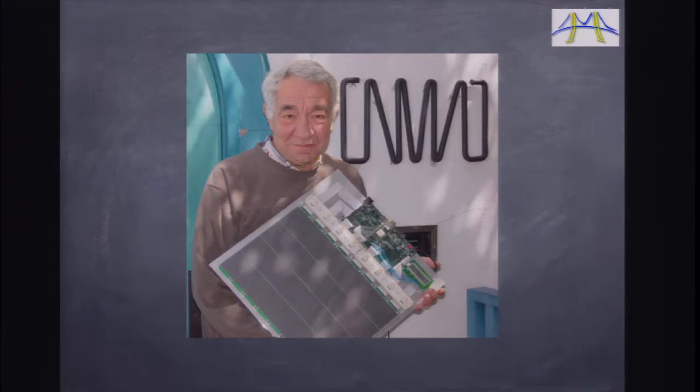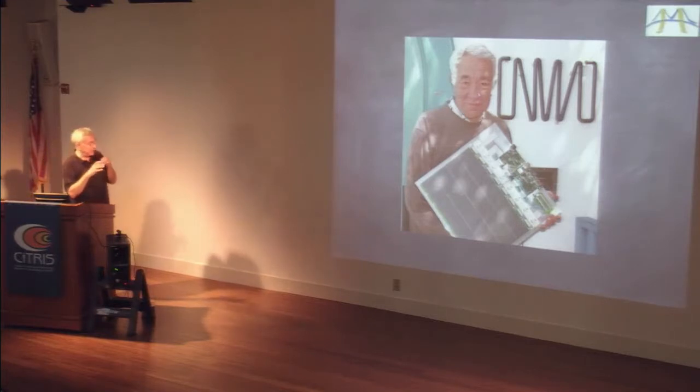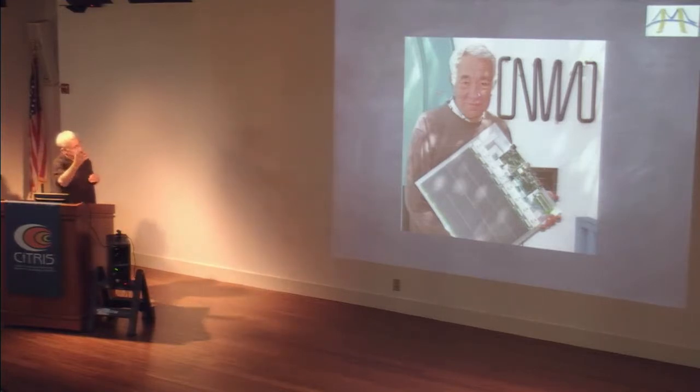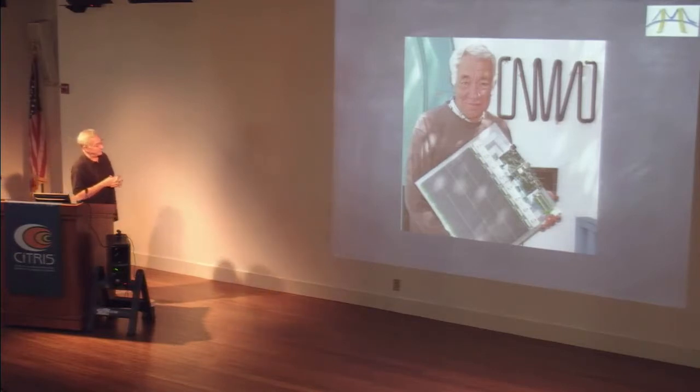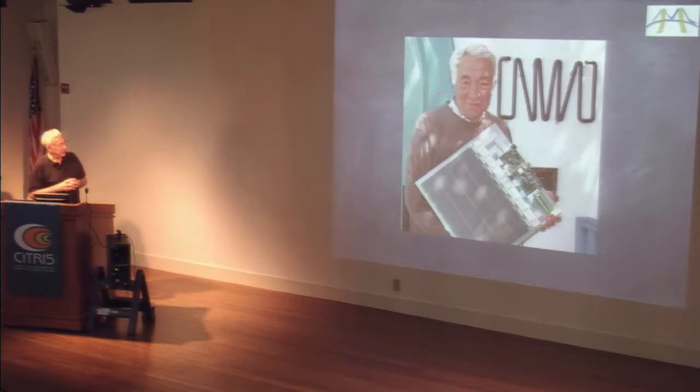So there are 3 dimensions associated with each of these and 32 of the pads. That's 96 total. Well, what we did to guarantee control intimacy here is we sampled those gestures at a high rate. And in fact, we sampled them at 1/8 the audio rate, which was near 8 kilohertz. And then we upsampled to the audio rate and sent them to the host computer over Ethernet. I've been playing with this thing now for about 4 years, and it's been behaving very well, and it gives me the kind of feel that I'm after in a live performance setting.